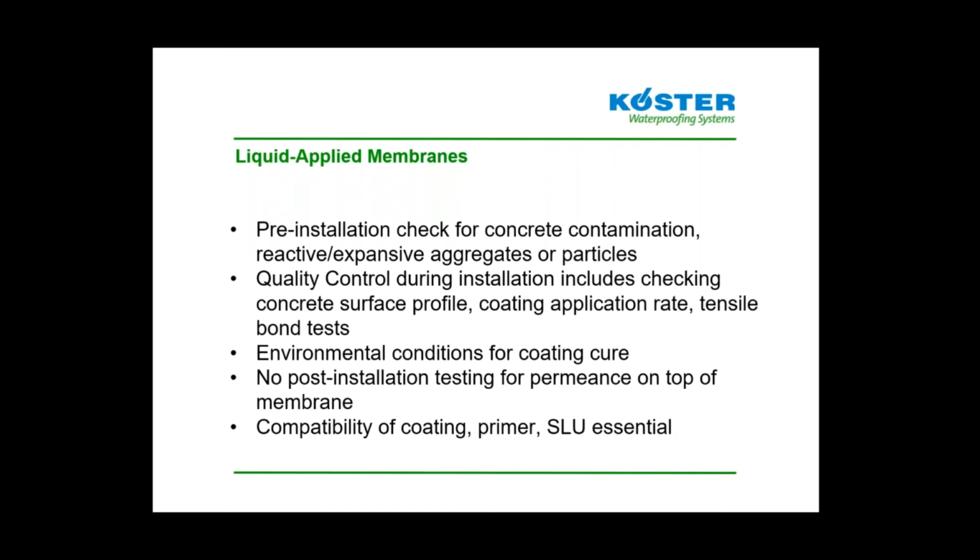So it may take several months after that coating's been installed for the water moisture in the concrete to reach equilibrium and work its way up near the surface. The only test of moisture suppressant system performance requires destructive testing by taking cores out of the concrete and measuring the actual E96 water vapor transmission rate, or the perm rating that we discussed earlier. Obviously, this is a destructive test that requires several months.